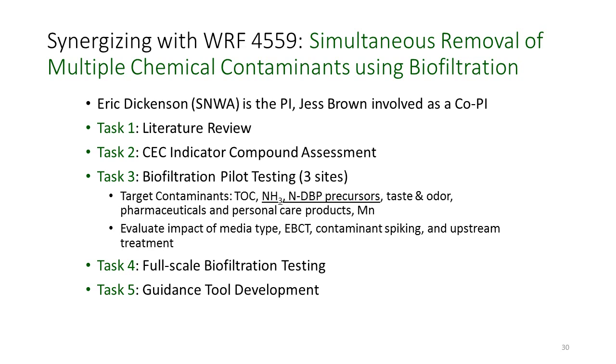The target contaminants that the project will be looking at, of course, are TOC or DBP precursors, but ammonia, N-DBP precursors, taste and odor, pharmaceuticals, personal care products, and manganese have really been identified as the main contaminants of concern in these source waters. We're focusing the piloting on the impact of media type.